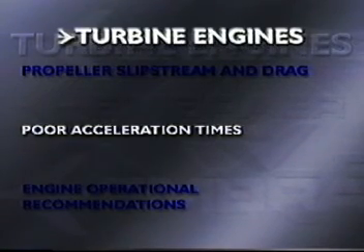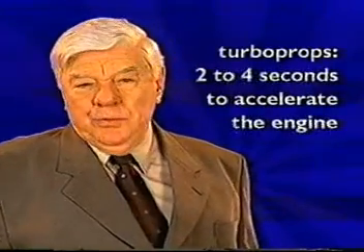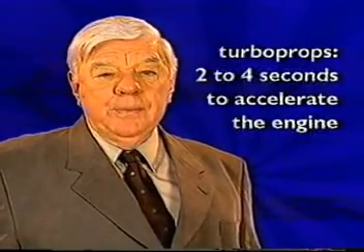Poor acceleration times. In a turboprop installation, increasing power results in the required thrust being supplied quickly, something about 2 to 4 seconds to quantify what we say. Unfortunately, the turbofan engine is not that fast in respect to acceleration times.